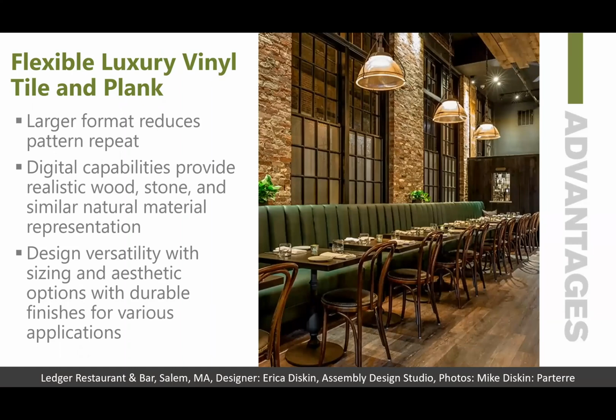So advantages include larger format, which reduces the pattern repeat that is available, digital capabilities with all the amazing finishes and looks and aesthetics that we have with LVT, and design versatility with the sizing and the aesthetic options, with a durable finish for various applications. So you may find that certain applications may not be appropriate for loose lay versus glue down, and glue down is the more appropriate product to utilize. So understanding what the requirements are and then evaluating the product type and the product that you're going to specify accordingly.